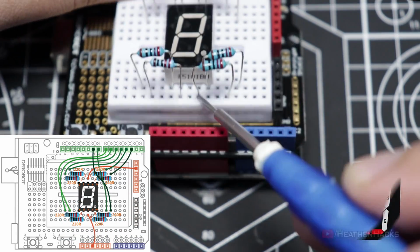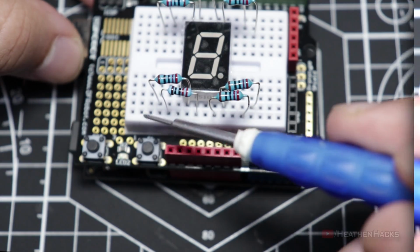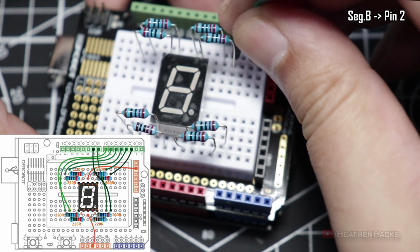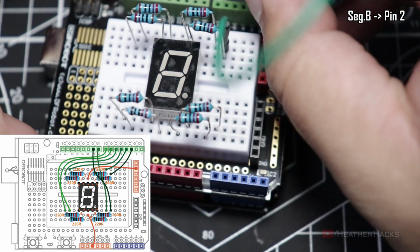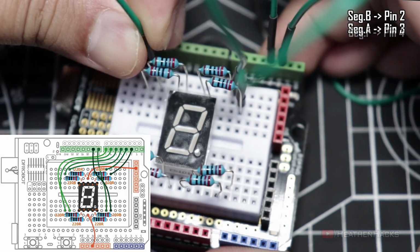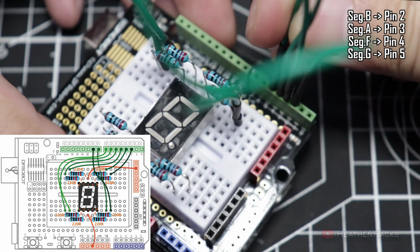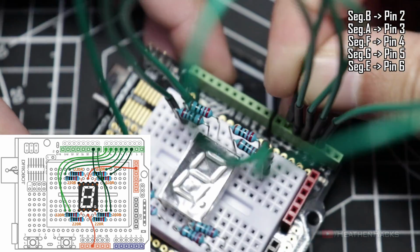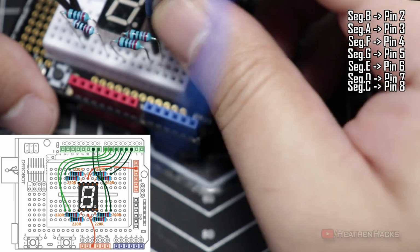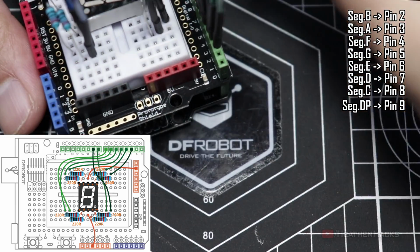Make sure that there are these blank pins at the middle because that's going to be used for power. Now let's connect the resistors to their designated pins. First, let's connect segment B to DFRduino's digital pin number 2. Segment A is connected to digital pin number 3, segment F to digital pin number 4, segment G to digital pin number 5, segment E to digital pin number 6, segment D to digital pin number 7, segment C to digital pin number 8, then segment DP to digital pin number 9.